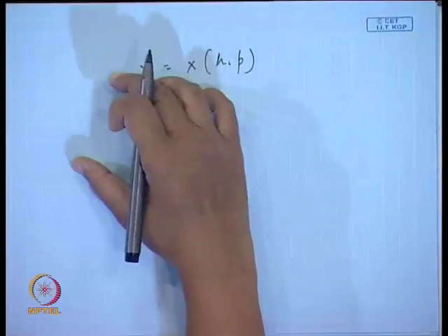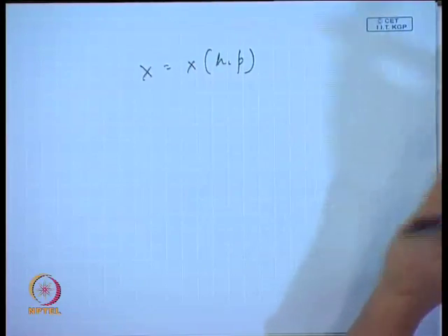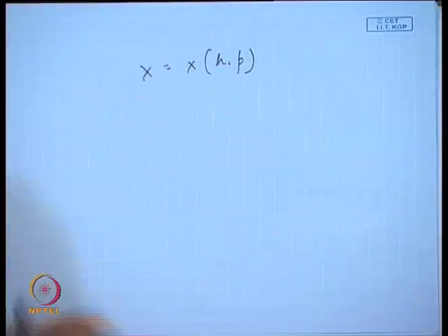We have to write the actual energy balance equation with the kinetic energy, potential energy, all the terms. From there we have to find out the proper expression of enthalpy, and that has to be substituted in the pressure drop expression, and it has to be done accordingly.